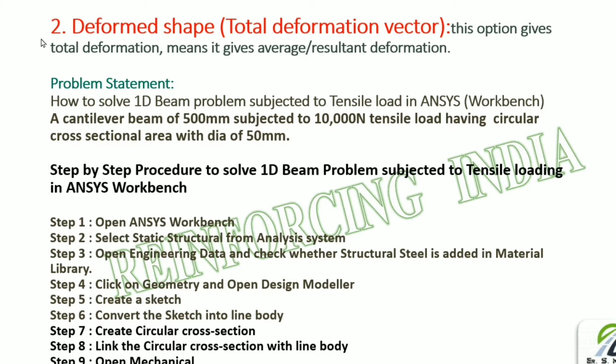We will see one problem statement. How to solve a 1D beam problem subjected to tensile load in ANSYS Workbench. A cantilever beam of 500 mm subjected to 10,000 Newton tensile load, having a circular cross-sectional area with a diameter of 50 mm.